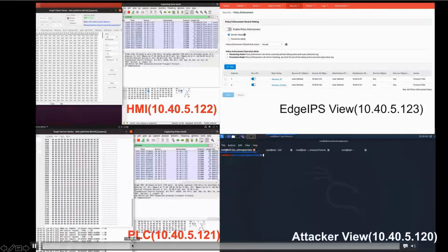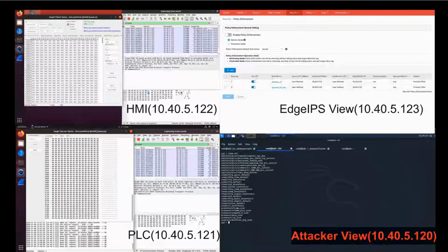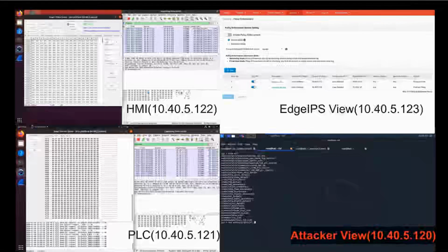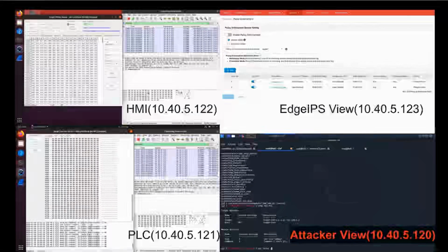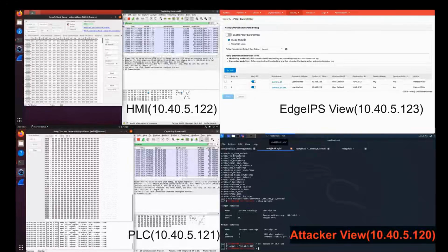And then, before we perform the attack, we set up our rule for network whitelisting, and make sure to use a module to perform the attack. We want to make sure of our Siemens exploit attack, so we perform the PLC S7 exploit. At this moment, we have not enabled any security. Without any security, we just set up the target. We want to send a command to the PLC.